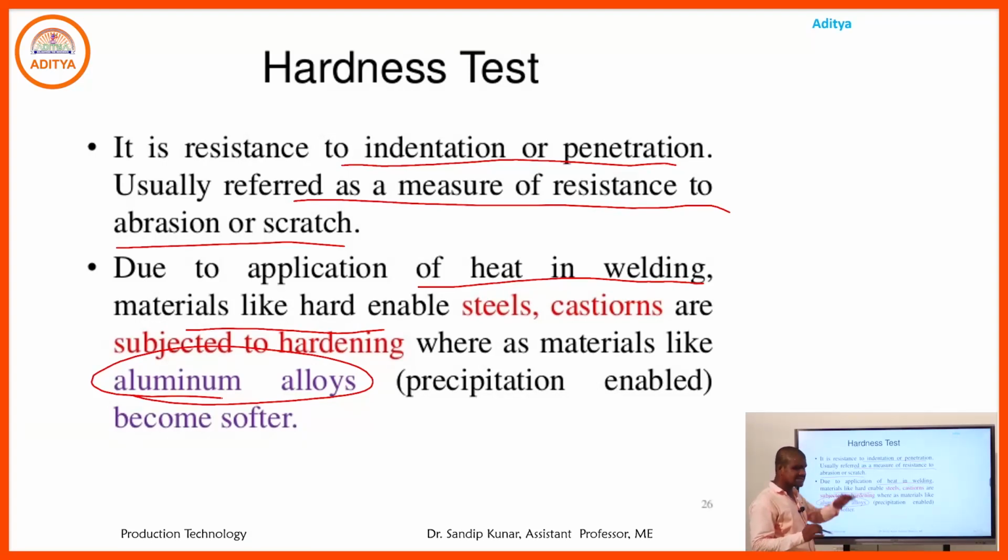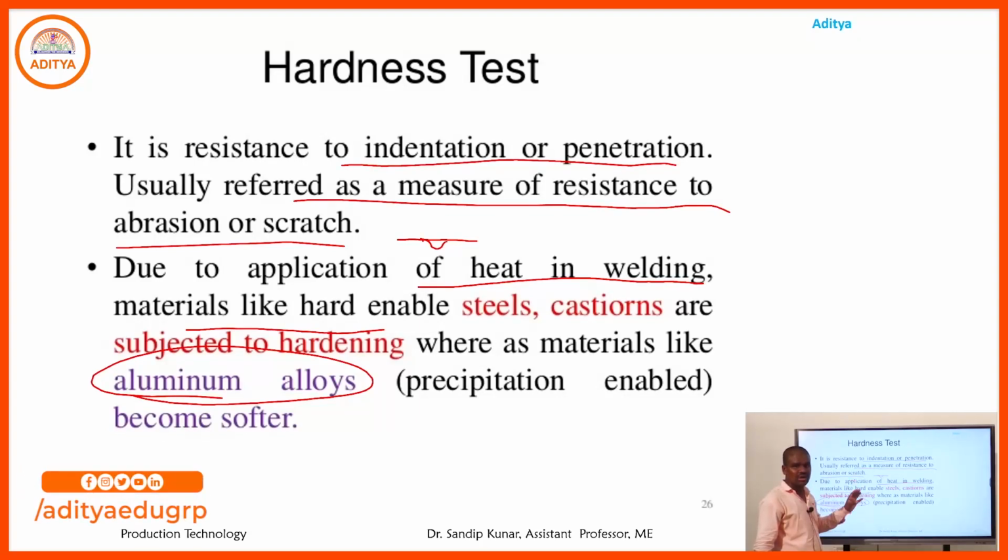When we apply pressure or load on that joint, some scratch or indentation will form, and depth will be generated, and based on that we collect the hardness data. Up to that data the weld quality is good, otherwise the weld quality will deteriorate.